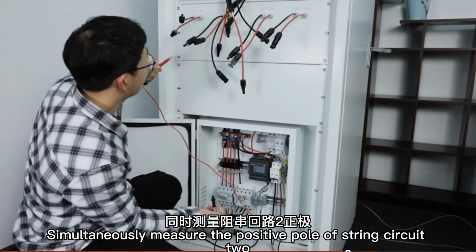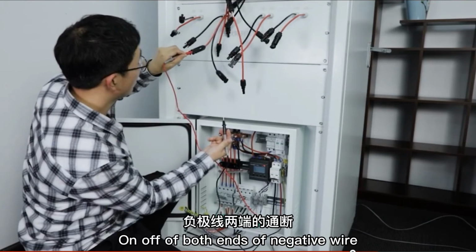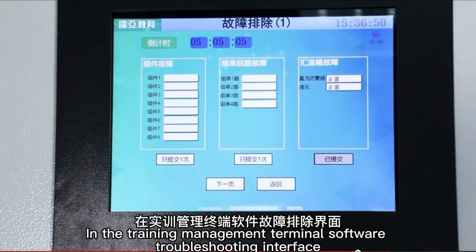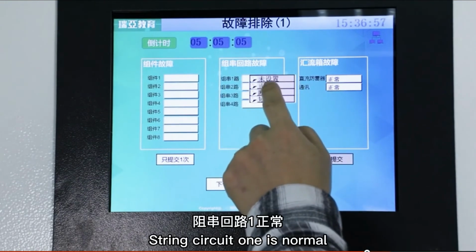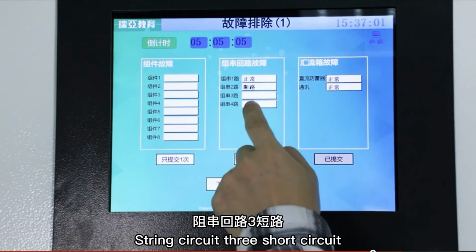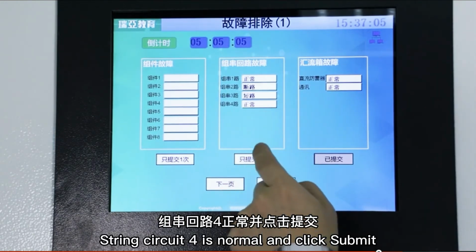Simultaneously measure the on-off of both ends of the positive pole and negative wire of string circuit 2. The result shows that there is an open circuit in string circuit 2. In the training management terminal software troubleshooting interface, select string circuit. Select a fault cause in sequence. String circuit 1 is normal. String circuit 2 open circuit. String circuit 3 short circuit. String circuit 4 is normal and click Submit.